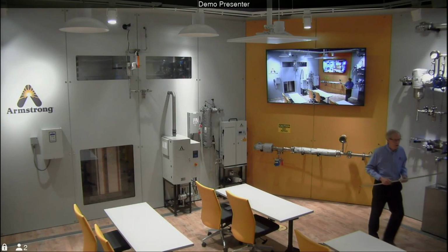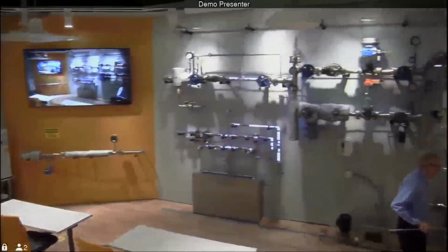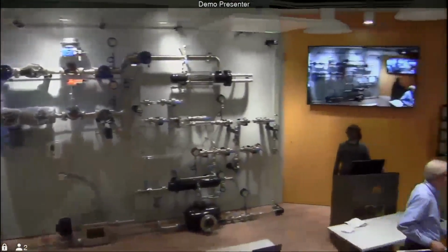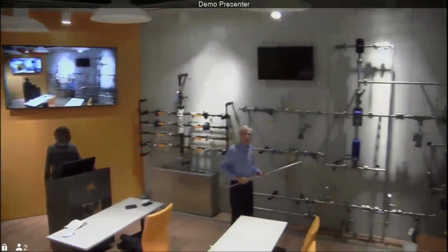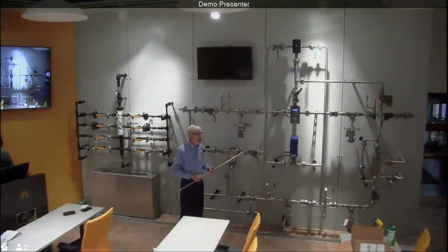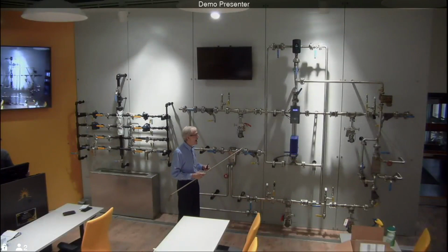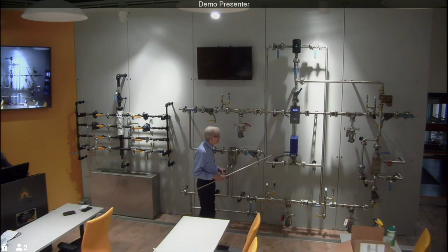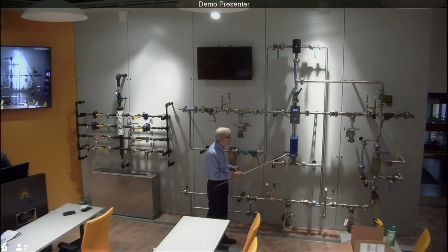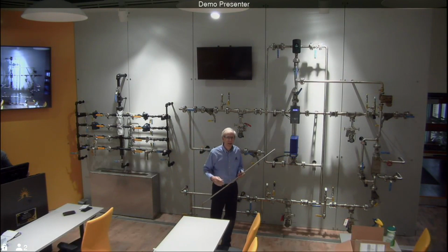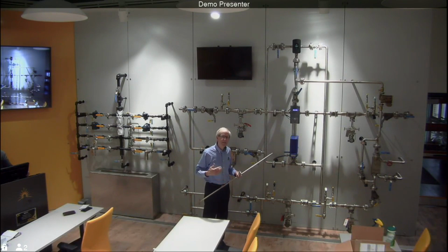As we move now toward our north wall, here we have a hot water temperature control system and the ability to vary the makeup of our zones, mixing hot and cold temperatures. We have 2 different forms of hot water temperature control valves. One, an EMEC type valve for industrial applications, another, the brain for institutional applications, as you might find in hospitality or in healthcare. Either one of these devices has the ability to maintain hot water temperatures plus or minus 1